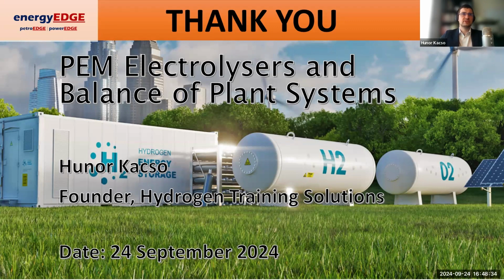So therefore, it's going to be around 60 to 66, potentially even 70% efficiency on very high efficiency electrolyzers. If you include heat recovery, you can achieve very high efficiencies, but very few systems include heat recovery. You can read about 80% efficiency on PEM electrolyzers, and that is going to require heat recovery to be included in that calculation.